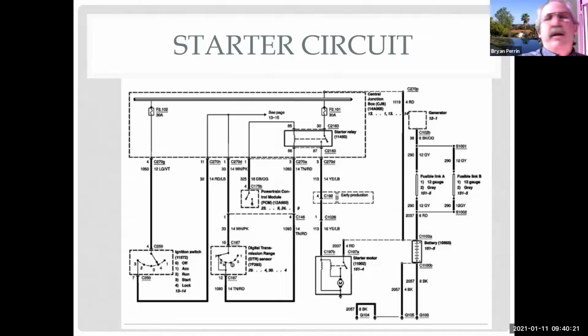So you can see there's a lot to just getting the engine to actually crank over when you turn the key. And that's why people go, my engine's not cranking over. What do you think it is? Well, I think it needs to be looked at. I mean, is the battery good? Are we getting a signal at the starter telling it to start? Is the starter relay working? So we can see where we go different places. Sometimes the starter is not easy to get to. Sometimes the starter is 5 hours underneath an intake manifold. I can't get to it to test here.